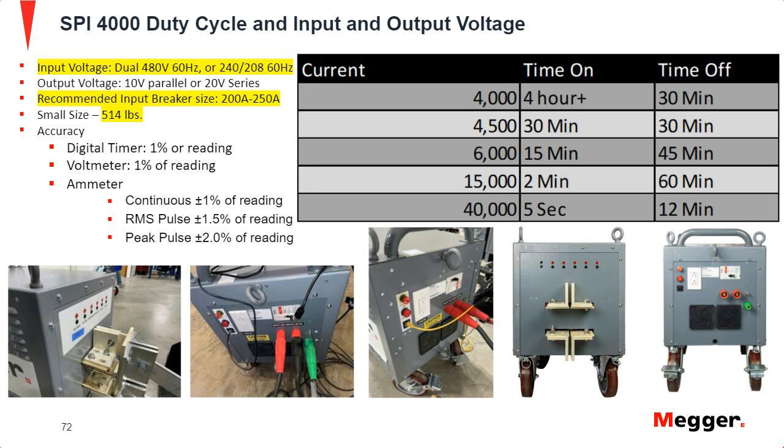That's why you'll see techs out in the field say you can actually grab these cables as you're performing these tests, which is not what we recommend, but it's because of the low voltage being pushed. You don't have to worry too much about the voltage rating, because all primary injection test sets are typically going to be using a low compliance voltage.